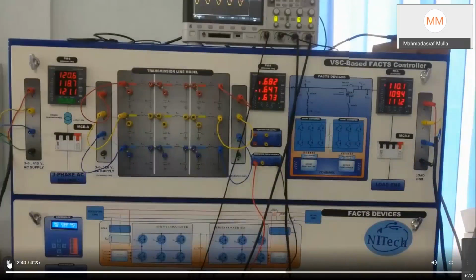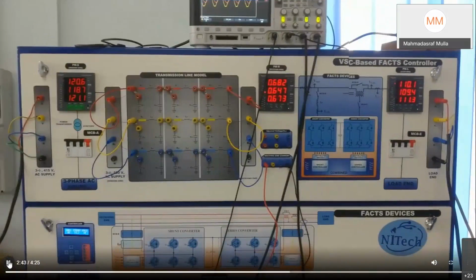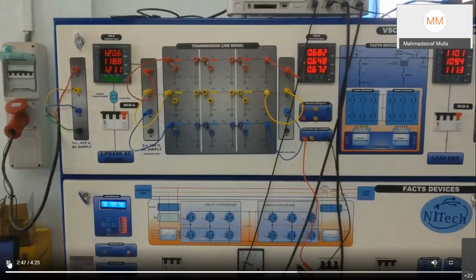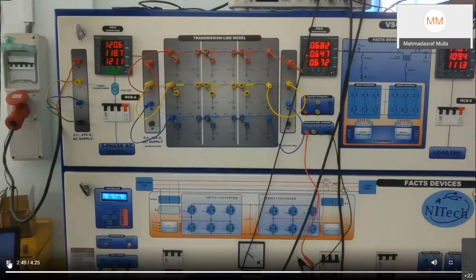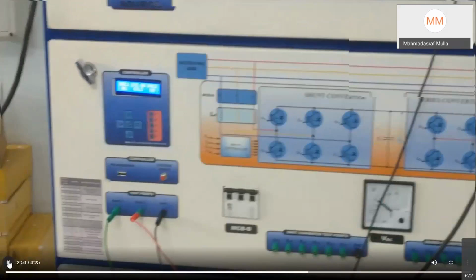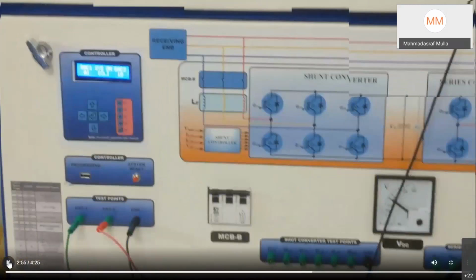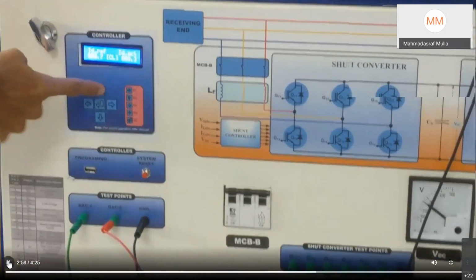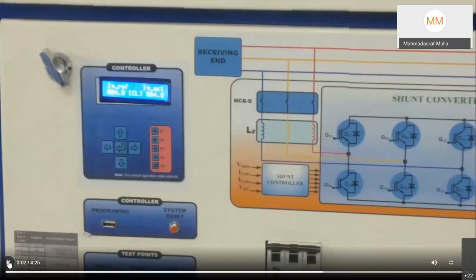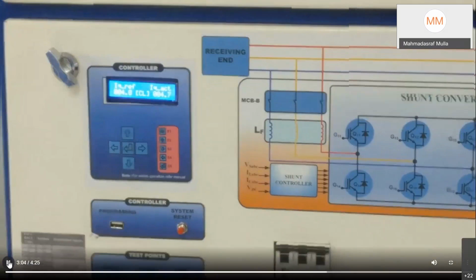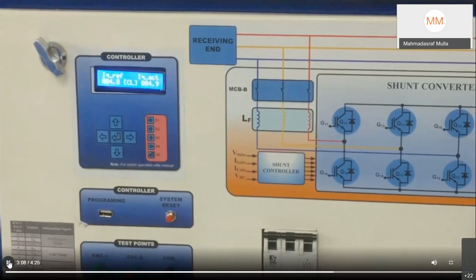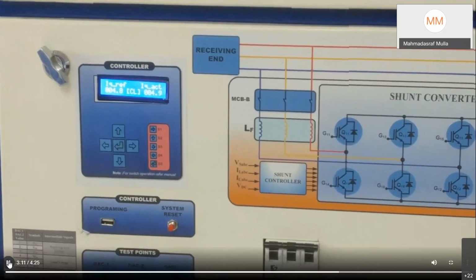Now we will see how this is happening. As I turn on the compensator, my PI will take some Q reference. You can see the Q reference value over here. So my algorithm is setting some point of IQ reference, and using that only my compensator is taking leading current.